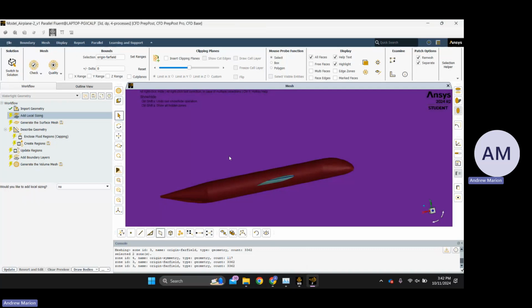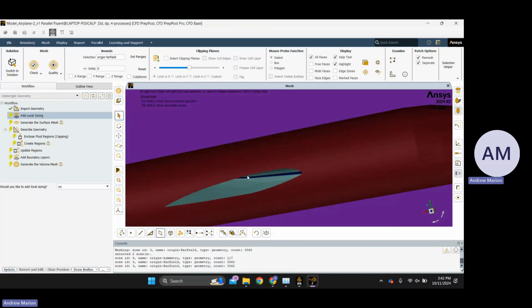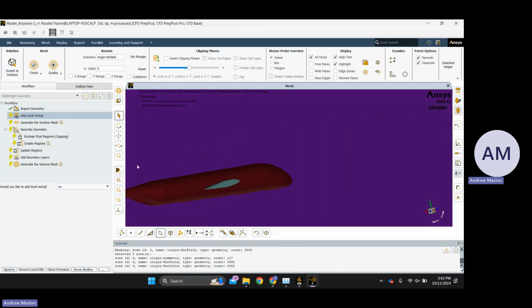There's two ways of doing that. You can either, when you're CADing it in SolidWorks, do a thin surface and make it literally hollow. Or when you import it and put it inside the fluid domain, depending on whether you're using SpaceClaim, DesignModeler, or Discovery, how you select this tool might be different.